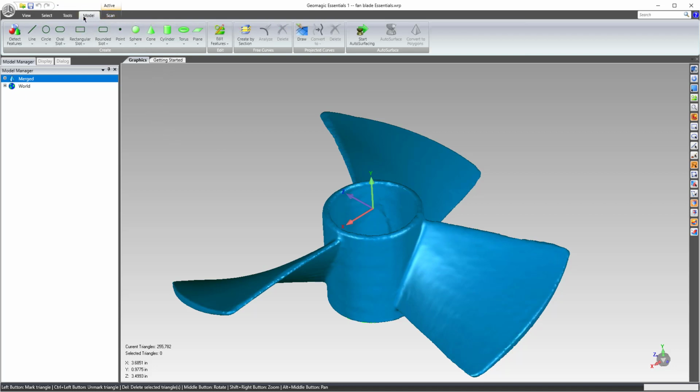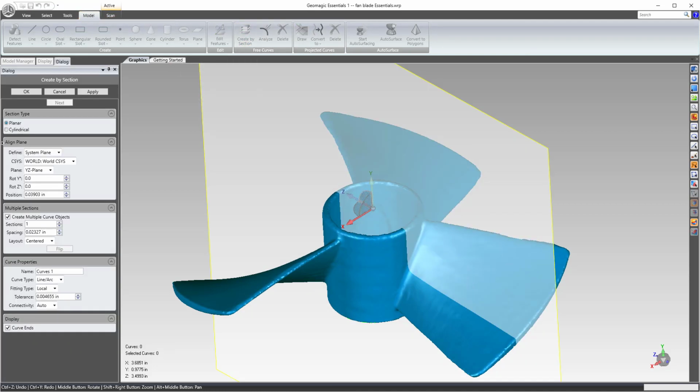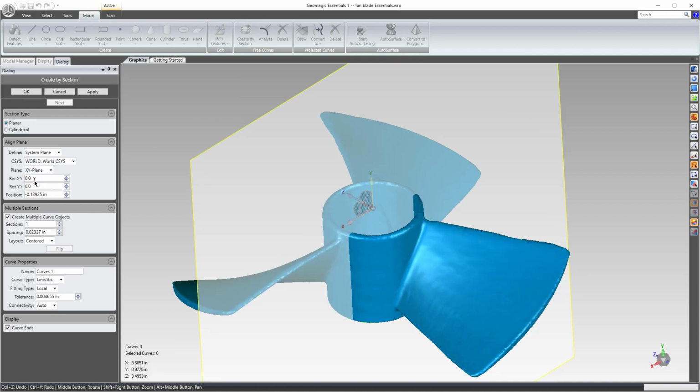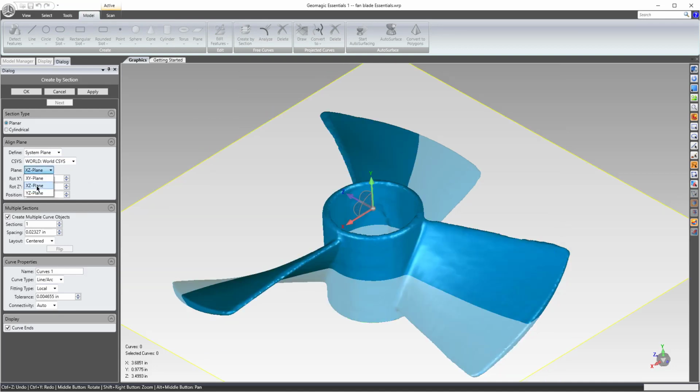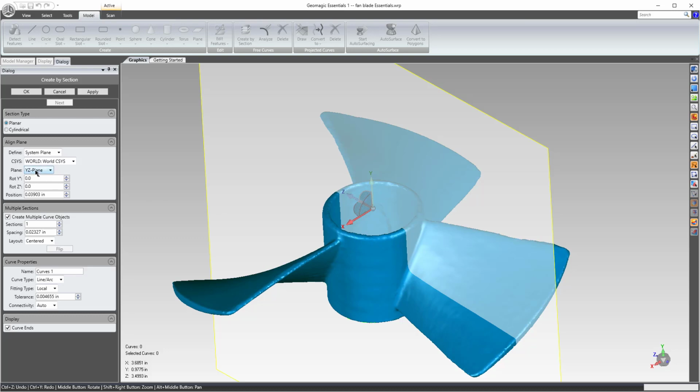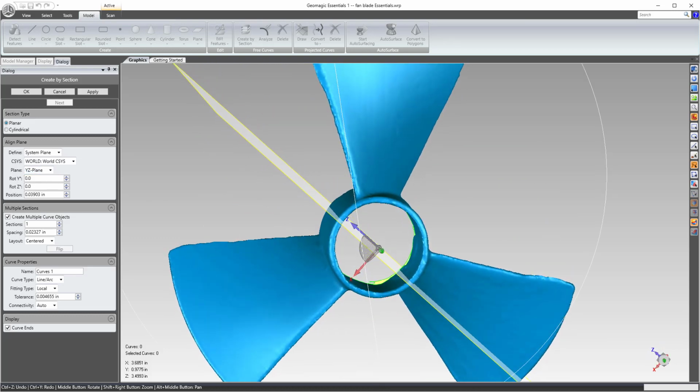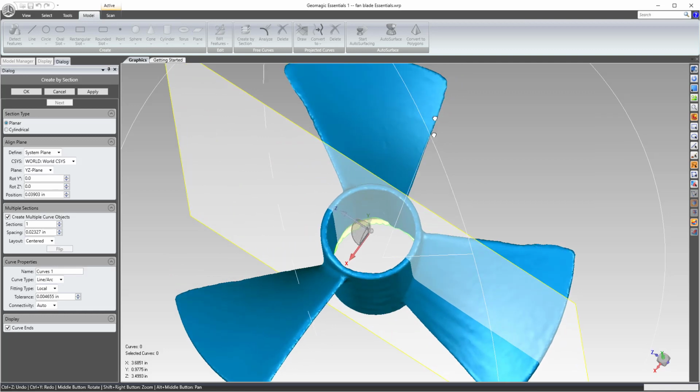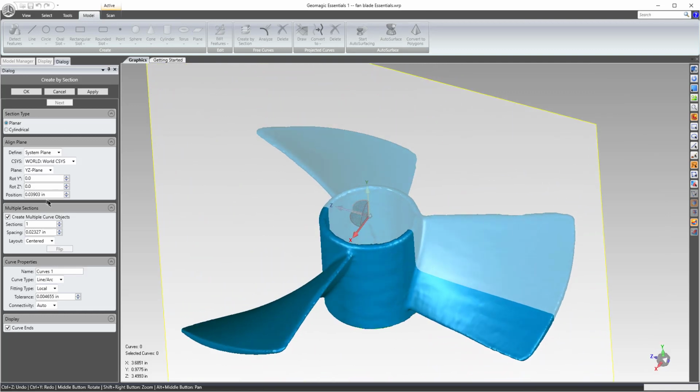So the first thing we're going to do is go ahead and cut a cross section. And you see I can actually toggle and change the cross sections over here. So I'm going to go ahead and use the YZ and slice through in that direction, and then make sure that the position is at 0. So it'll move it so it intersects the 0.